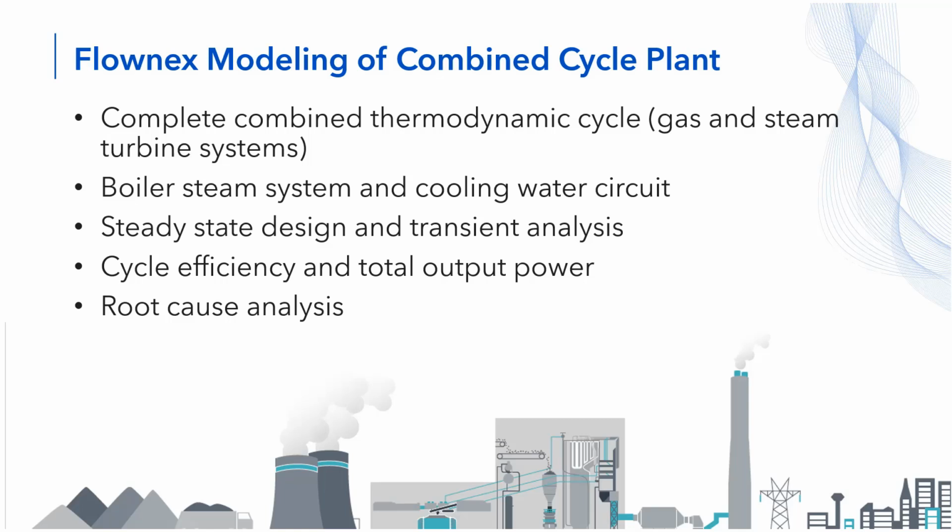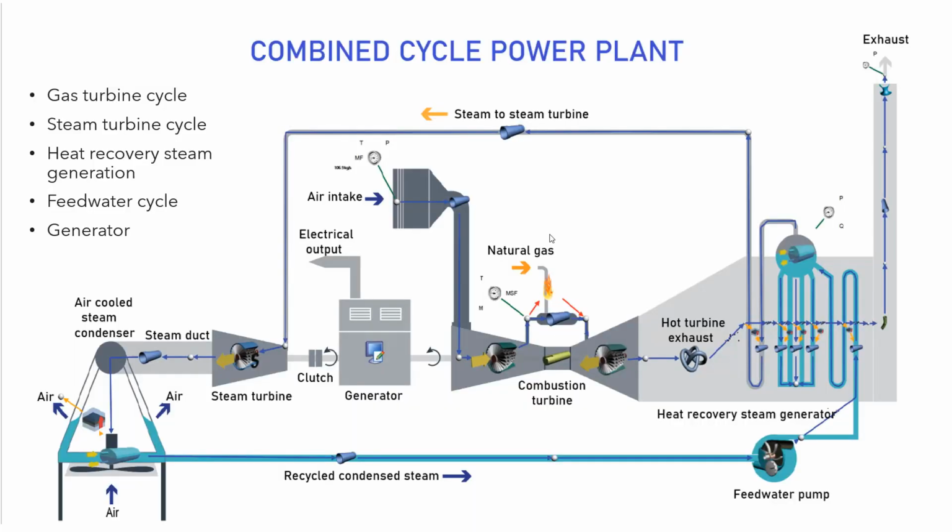The good thing is that for the design and analysis we can run steady state and transient analysis, and we can have a calculator to find the values for the cycle efficiency and total output power. And in this way, we can run the model for different inputs, for example, changing the fuel gas that we have.